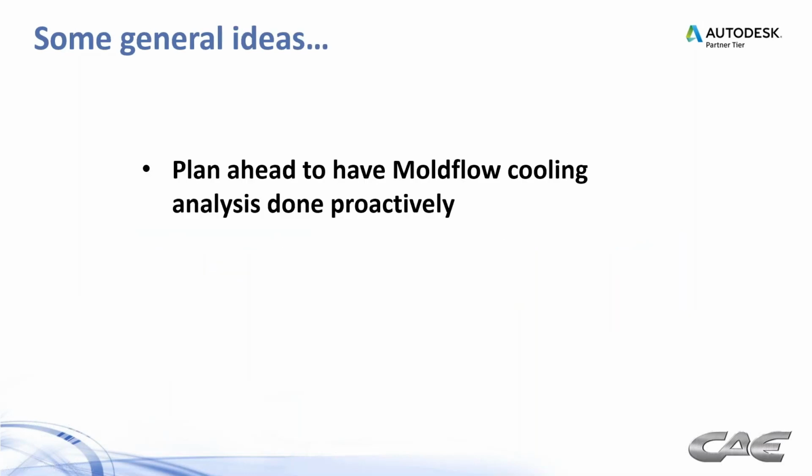So here's some general ideas. Make sure you plan ahead to have Moldflow cooling analysis done proactively. Don't wait till you're ready to cut steel on a mold to do this. By then it's often too late, the clock's ticking. Make this part of your everyday activity when it comes to designing and manufacturing molds.